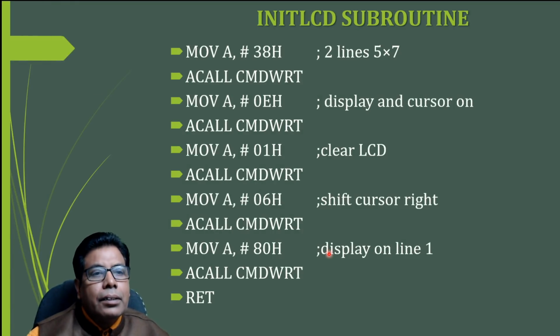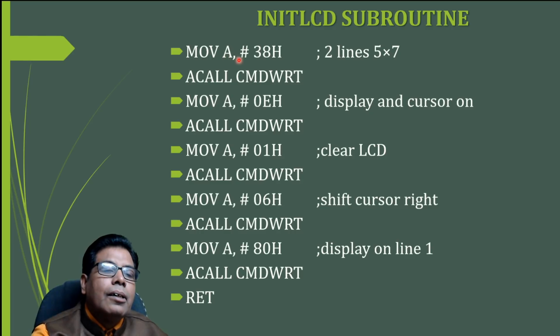Then the initialize LCD subroutine, INIT LCD. So first of all we load A with 38. This hexadecimal code defines that the display is 2 lines and 5x7 matrix.